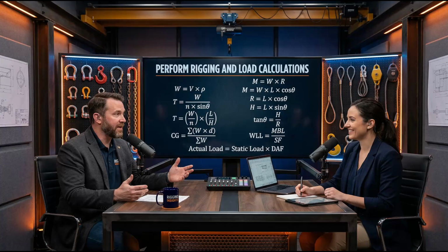A crane engine vibrates, the boom flexes, the hoisting cable bounces. Inertia fights against the upward pull. Right. To account for the kinetic energy introduced by movement, engineering calculations mandate the use of dynamic amplification factors, or DAF.